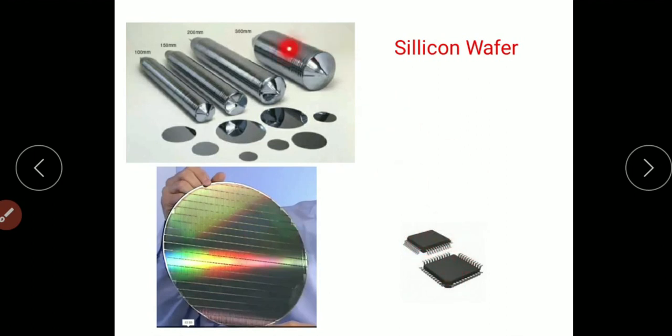So what is the process? First of all, you have to cut these silicon ingots into silicon wafers. Then you have to implant different layers. You can fabricate the circuit on these dies. Then each die works as a chip. These dies can be packed in sealed covers using material like plastic. Similarly, many metals we can use to pack. What is the necessity of packing? To protect from the outer world, like temperature.